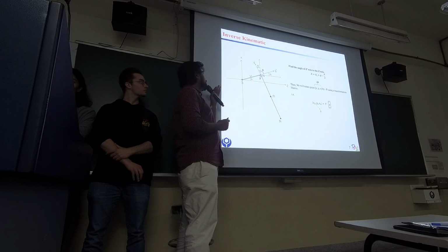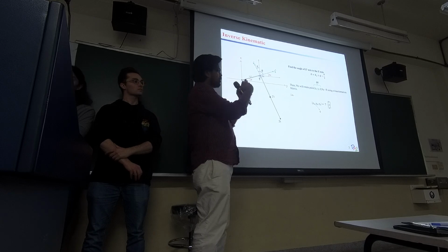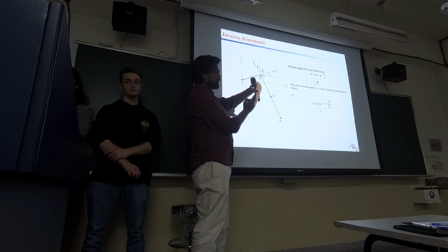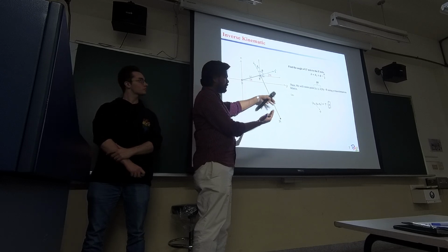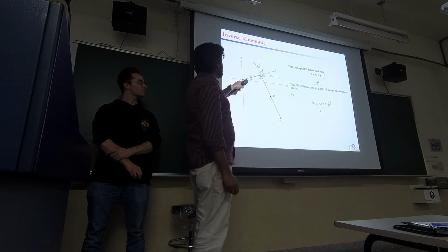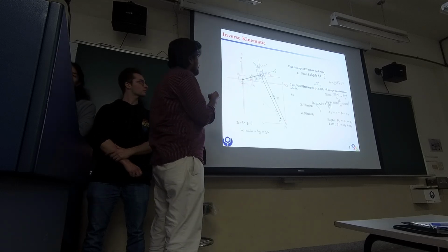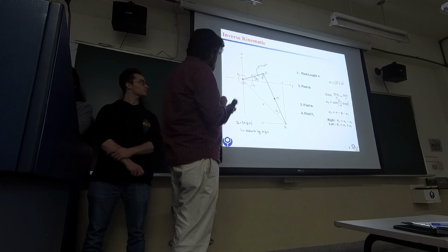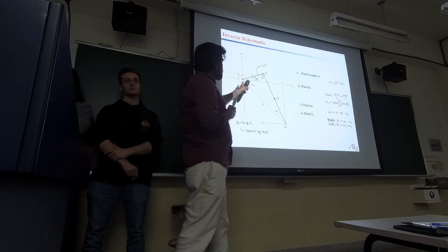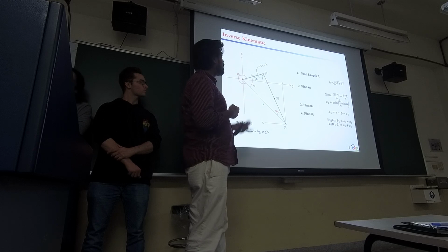Now we are seeing the robot from the front, and what we observe is that the robot is like that, and this leg is like that, so we cannot mention that one. That's why at this point we are seeing it from the front. So this is the point that we have mentioned, and now these are some angles. We have to find theta 1, and phi is constant. This is the x coordinate, this is the z coordinate, and this is the y coordinate. Now we have to find the length of A.